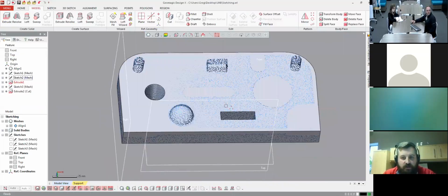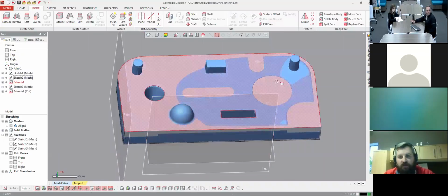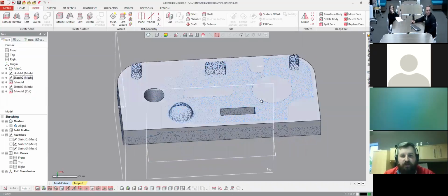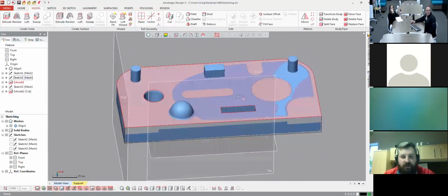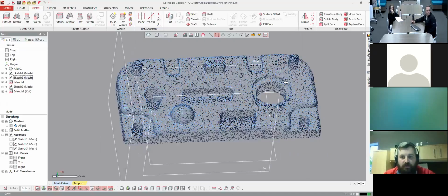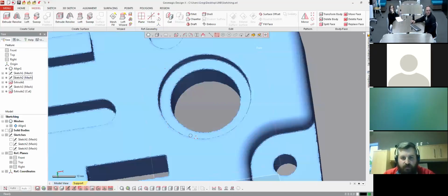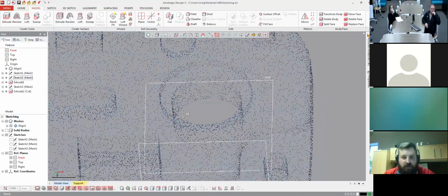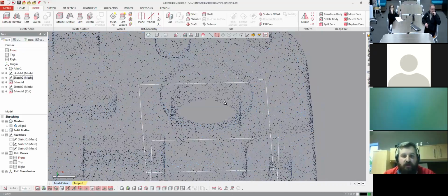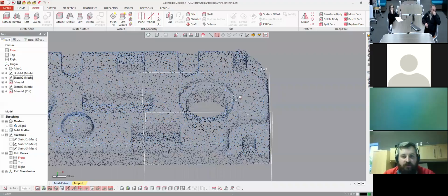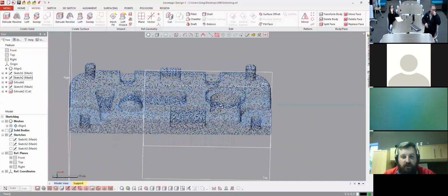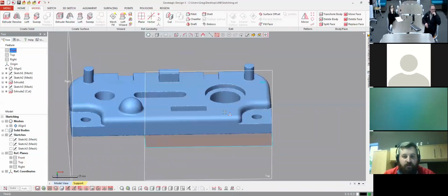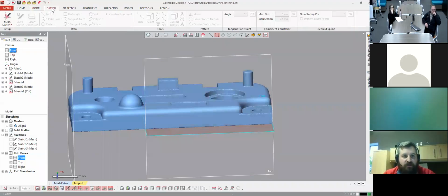So the next step we're going to do is also use sketches to create a reference to build other sketches off of. For this particular feature, we're going to do it as a revolve feature instead of an extrusion. We can create this whole profile all in one swoop, swing it around an axis, and then we can get a nice cut from there. Another thing I can do is create what I call reference sketches.